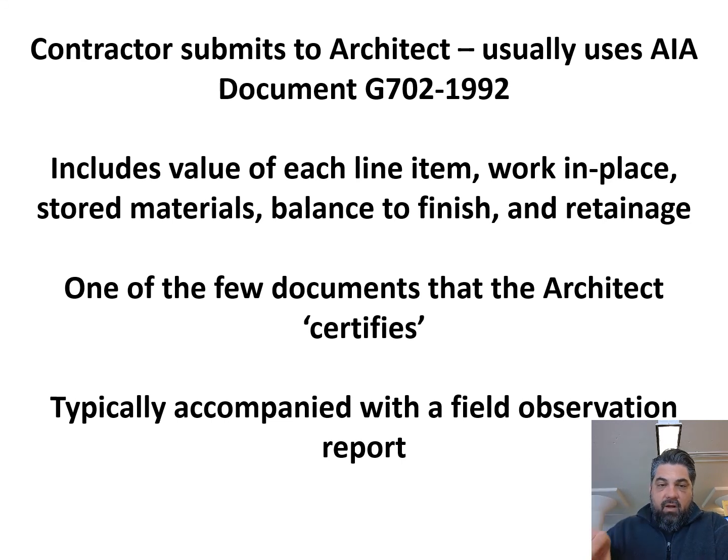The next column on the pay app will be the balance to finish, and then any retainage. I don't think we've talked about retainage yet. So retainage is a process in which the owner retains some of the value that's complete as an assurance, not insurance, but assurance that the general contractor will complete their work.